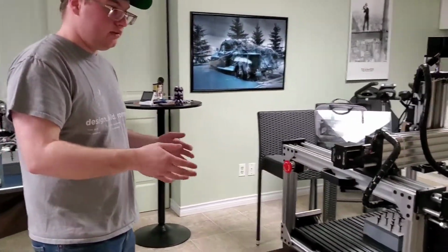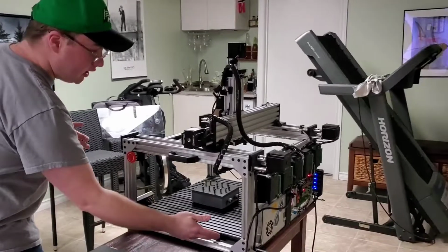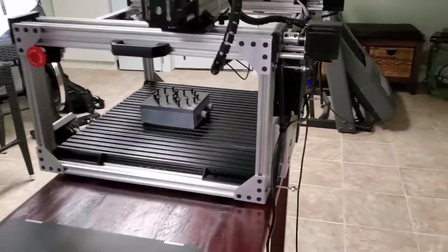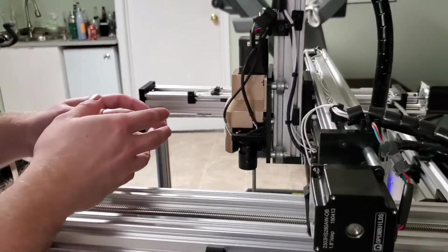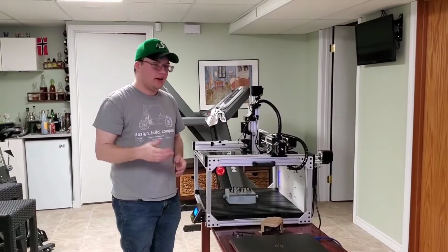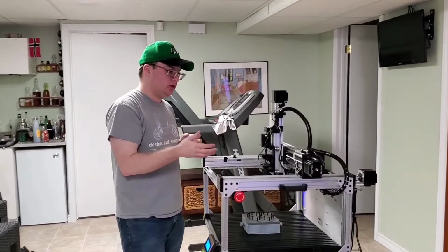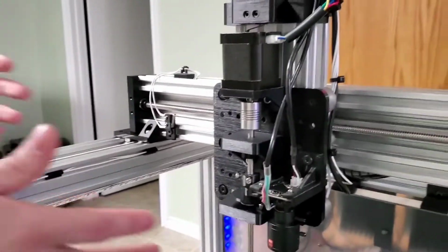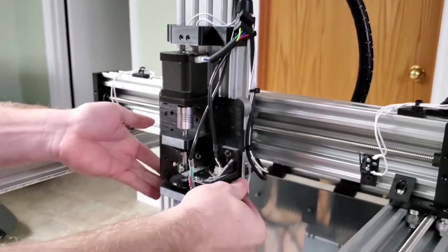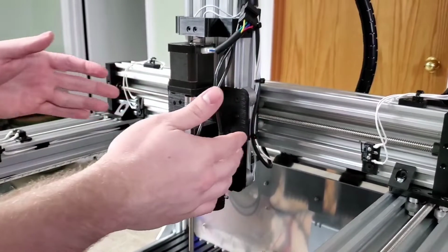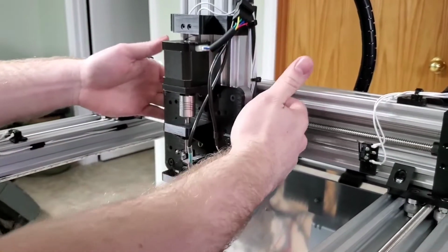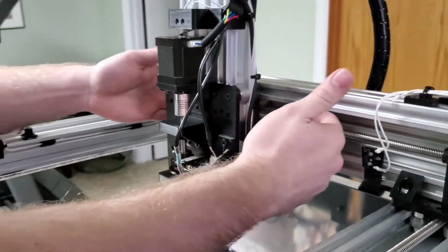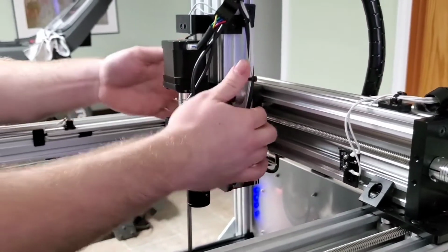Finally, we have a few more elements like the bed brackets that we've designed, and then the screwdriver module, which we're about to get more elaborate into. Alright, so now I'm just going to give some more explanation on the screwdriver module since it's such an integral part of the mechanical. Looking at it here, the entire thing is mounted on a gantry plate. This gantry plate gives us an up and down vertical motion. The entire Z-axis is mounted on the X-axis right here, as well. So that's our combination there.